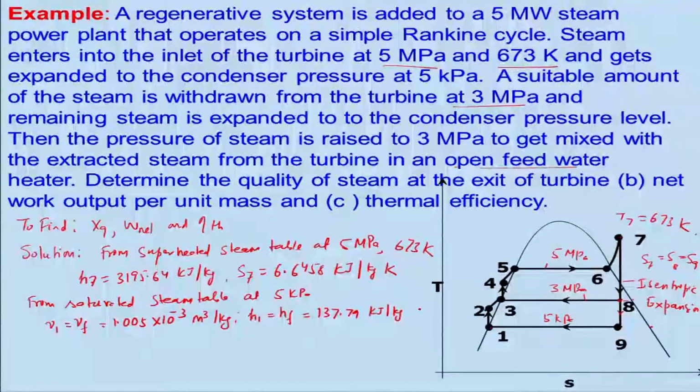And I can get Hfg, the heat of vaporization, which is 2423.66 kilojoule per kg, and I need also entropy, S1 is equal to Sf.